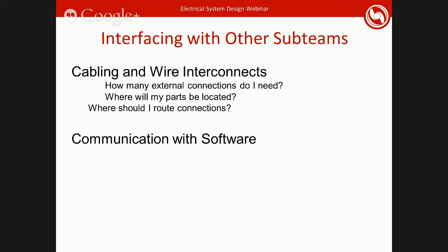Also, as far as interconnects, make sure that there's enough space to fit all of this cabling, because we do a lot of custom solutions. We deal a lot with wires going everywhere, wires between boards. If you're doing off the shelf, a lot of the store-bought connectors that you're going to get don't necessarily have the proper bend radius that you need. So make sure that all of that fits into the mechanical design.